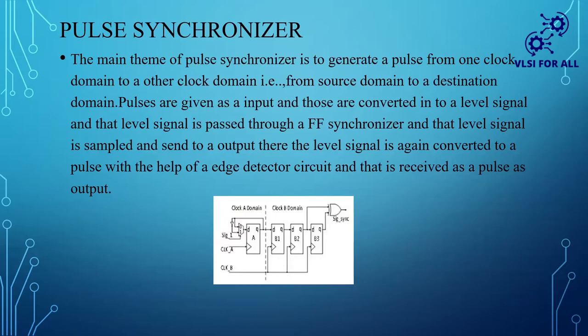Next, coming to the pulse synchronizer. What is the main motto, or the main theme, of a pulse synchronizer? Generating a pulse. The main theme of a pulse synchronizer is generating a pulse from one domain to another domain. That means generating a sample pulse on the destination side is known as a pulse synchronizer. That is, generating a pulse from one clock domain to another clock domain.